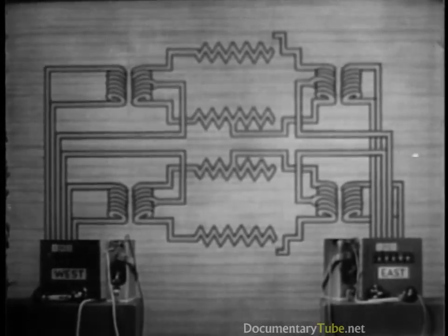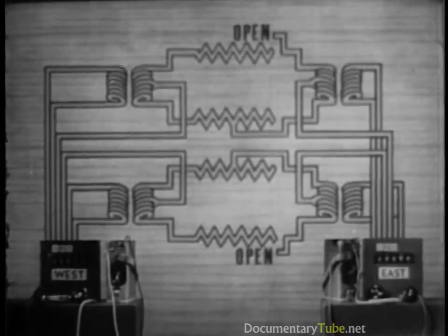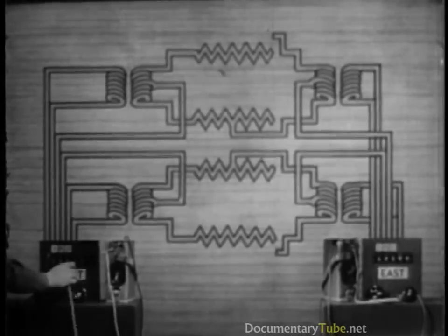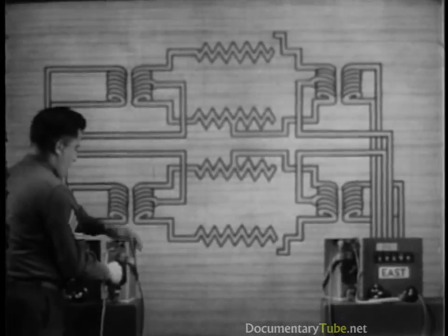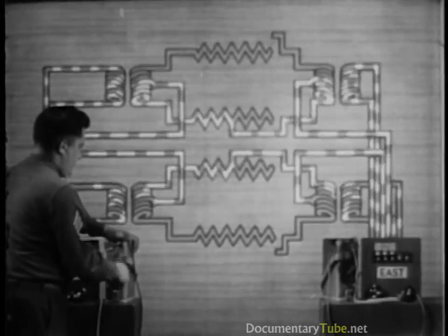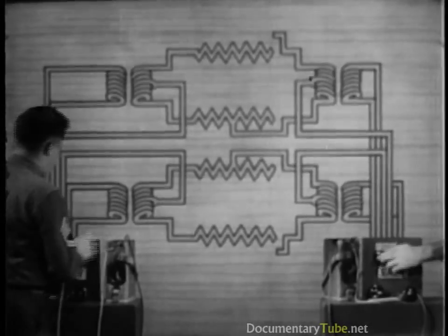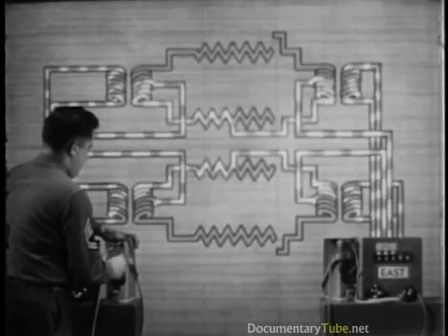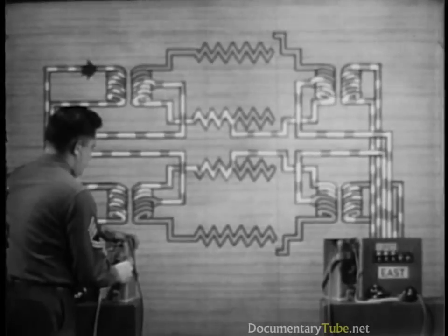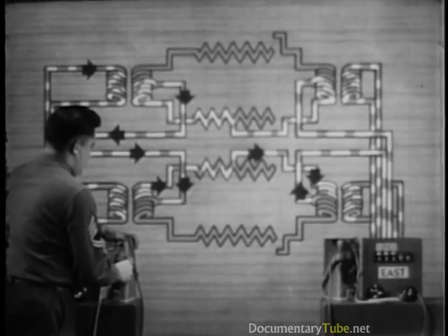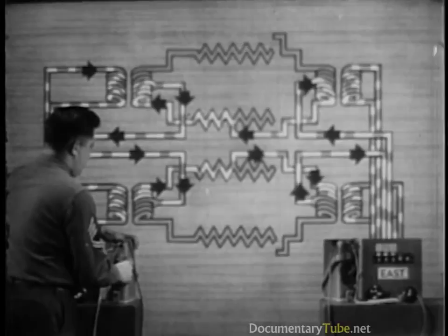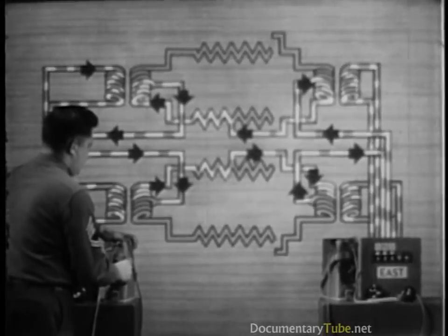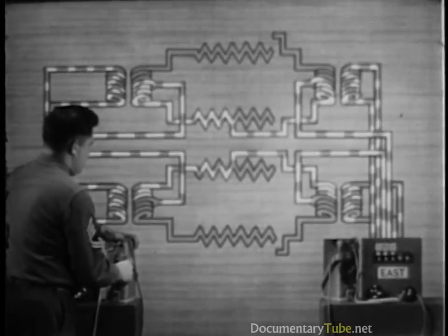What happens if both side circuits are open? This one's tricky. For now, both sets of repeating coils are unbalanced. Ringing on either side circuit, we find that current flows through every possible drop in the phantom group. The jack we ring on is, in effect, connected in series to the other 5 drops. Either side circuit then interferes with both the phantom and the other side circuit.